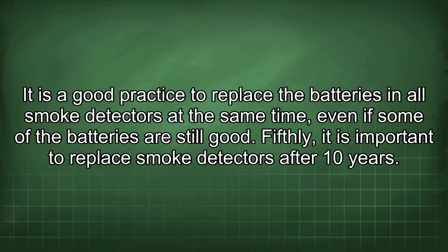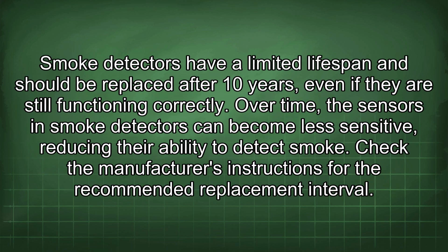Fifthly, it is important to replace smoke detectors after 10 years. Smoke detectors have a limited lifespan and should be replaced after 10 years, even if they are still functioning correctly. Over time, the sensors in smoke detectors can become less sensitive, reducing their ability to detect smoke. Check the manufacturer's instructions for the recommended replacement interval.